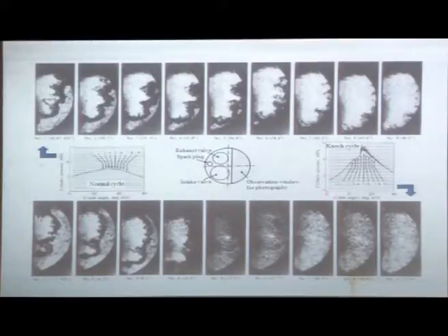Here this is a knocking cycle. So again, pressure on the y-axis and crank angle on the x-axis. So you see here, the first image is taken at this point, then second, third, fourth. Up to the third it's pretty normal. Three images are very clean. You see the flame front moving gracefully, trying to consume. But then in the fourth, you see the whole thing is just exploding. And once it explodes, whatever normal, systematic consumption was happening is all exploded.